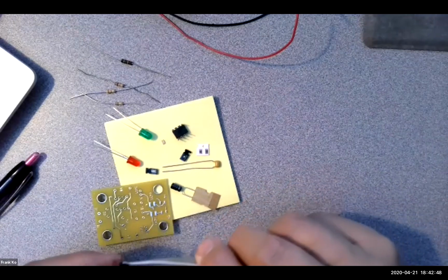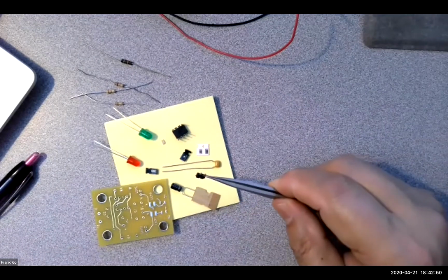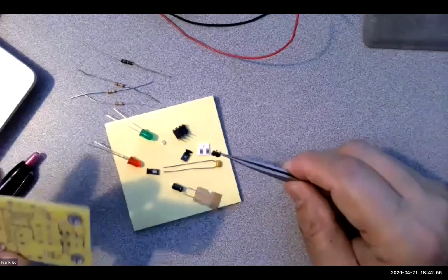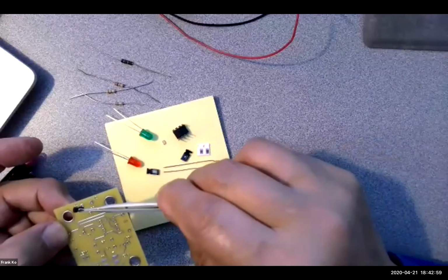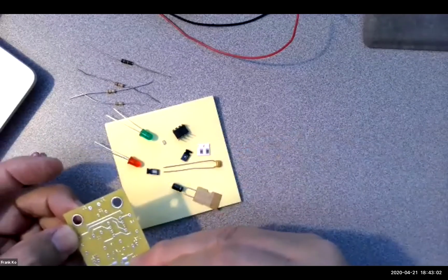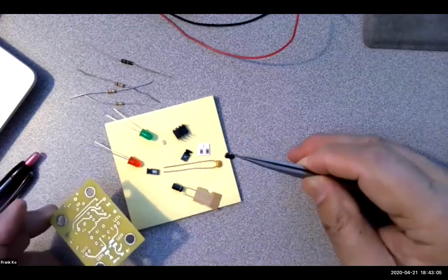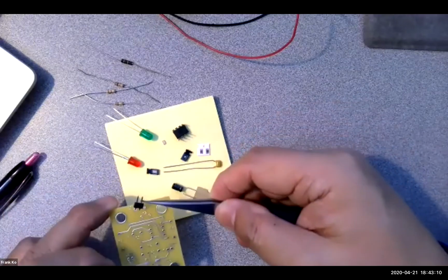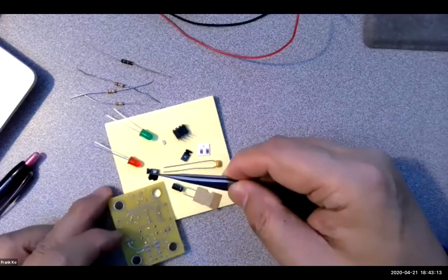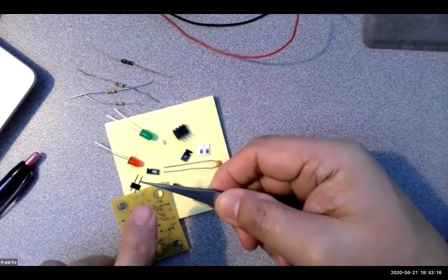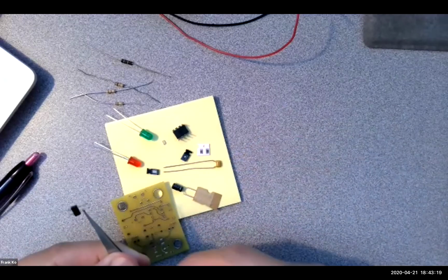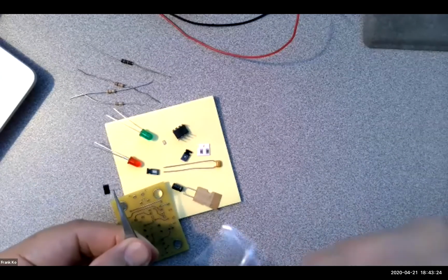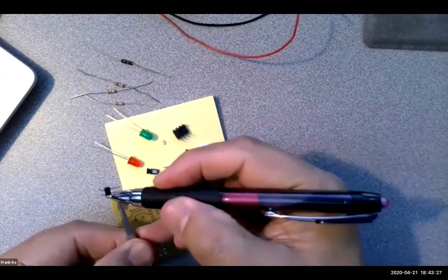These happen to be point contacts for the voltage source. And they are soldered onto here. This is your jumper 1 and jumper 2. Somebody was asking about the schematic in the Multisim, what was JS1, what was J2? Jumper wire 1 is going to be one of these, and jumper 2 is going to be the other one of these. And the recommendation here is, although they're connected together in tandem, you use a wire cutter to cut this particular piece in 2.